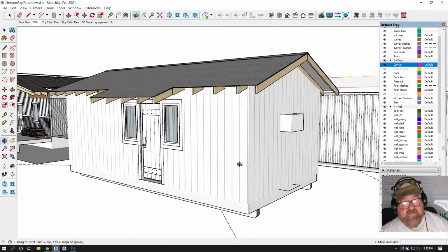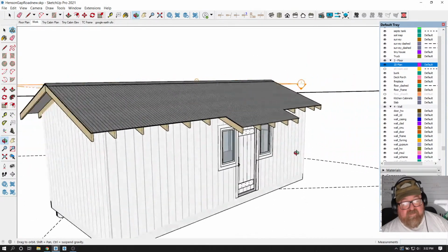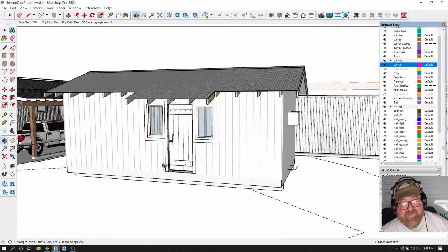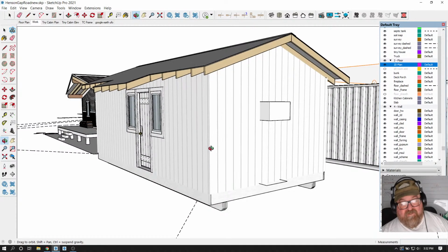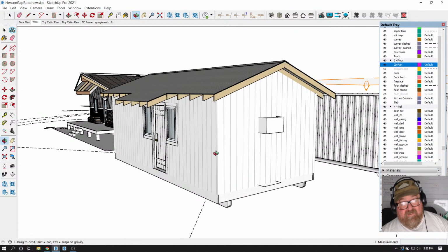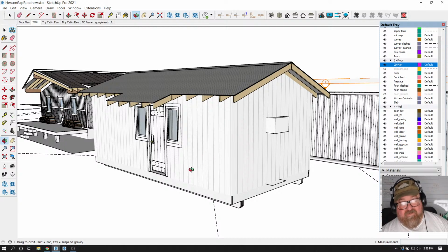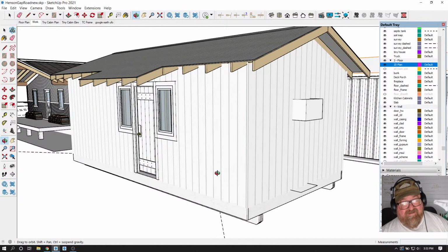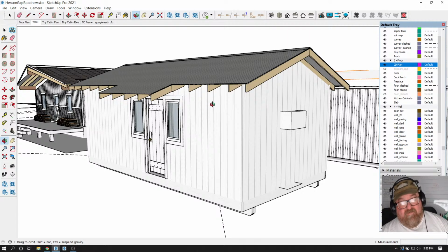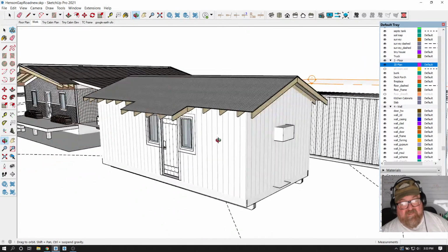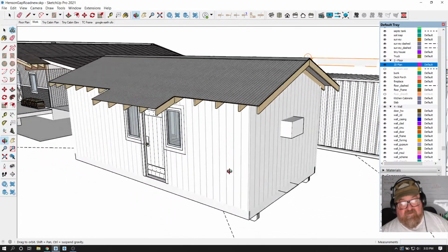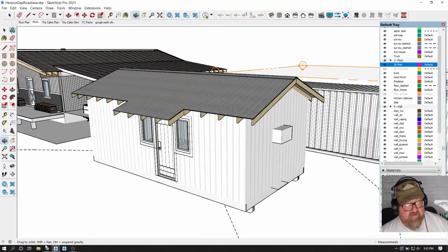Believe it or not, a lot of houses in the 70s were built like that, the spec houses. It was kind of crazy, and we didn't use 5/8 deck either. The first contractor I worked for was this Jewish builder, and I can tell you some stories. It was cheap. It was T111 over studs at 24 inches on center, just T111 straight to the studs, and the windows were nailed on top of the T111 instead of behind it. So anyway, this should be an interesting little build, and maybe I'll tell some stories as we go along.